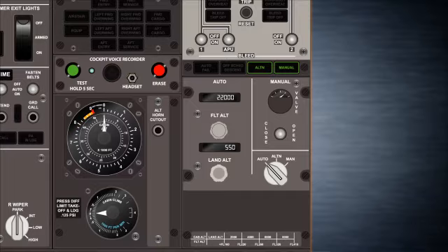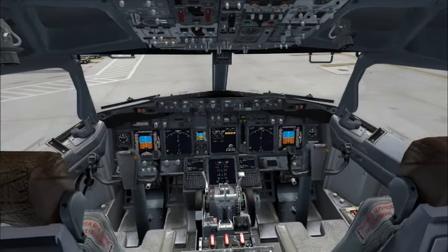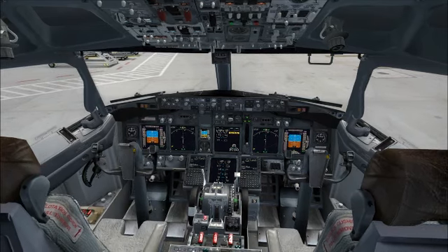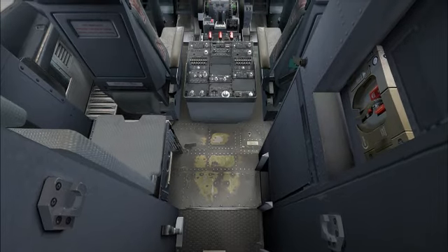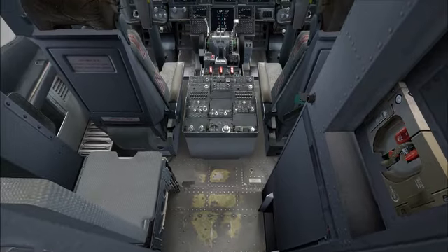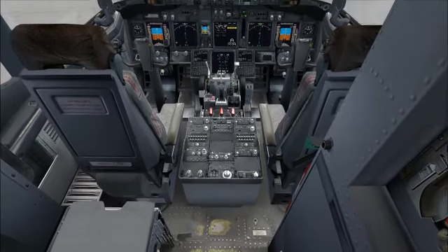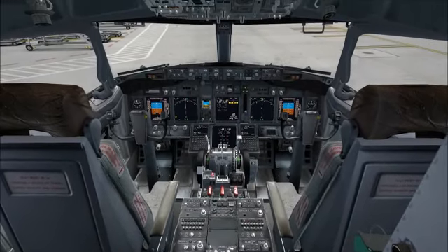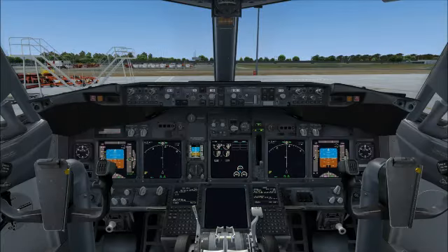The 737NG flight deck has its roots in the original Boeing 737s of the 1960s, and it shows. The 737 was the first Boeing jet airliner to be designed without a flight engineer, and the master caution system was developed to ease pilot workload. The system is centered around the master caution and system annunciator lights on the outboard ends of the glare shield. The master fire warning lights located outboard of the master caution lights are separate to this system and are covered in the fire protection lesson.